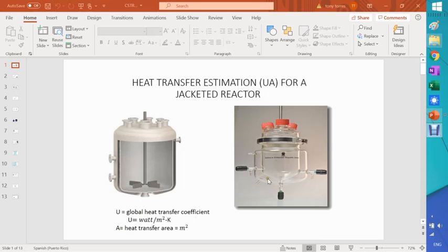Here I'm showing you typically a laboratory scale reactor with jacket. Okay, so it's kind of nice. I used to work in pharmaceutical, so I'm very familiar with both cases. This type of vessel, in the pharmaceutical area, is mostly a glass-lined reactor, just because we work with very highly corrosive material, and that's one. And the second big issue is that you want to avoid contamination of your product as well. So that's why you have pretty much glass-lined types of reactors.